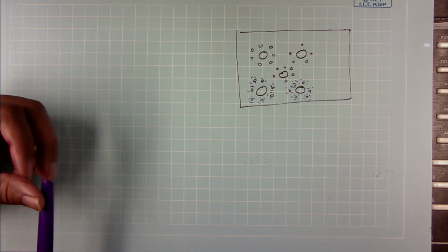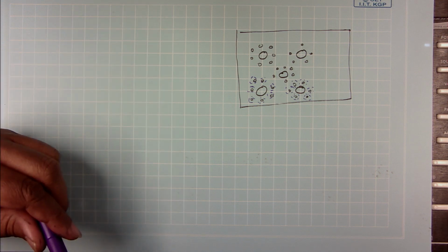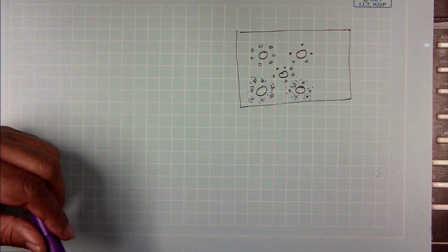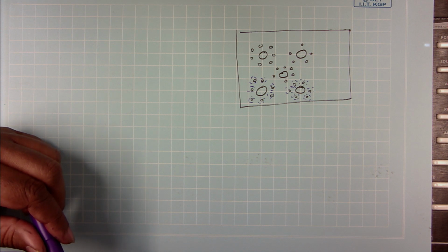Okay. So, there are two things that are happening, because the thickness of the liquid layer is smaller. So, they have less resistance. So, they are getting more condensation rate, and then if you have a big droplet, the majority of the condensation is on the perimeter, isn't it, just like in boiling.